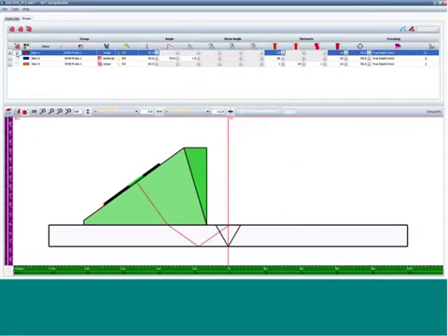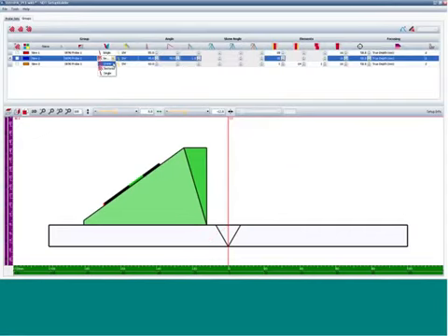Another type of group we use is called the sector scan group. And this is the most common type of group most people associate with phased array. In the sector scan group, again, we're going to use the same group of elements as our static focal law, all starting on element number 30 here. If I were to move that to element 1,